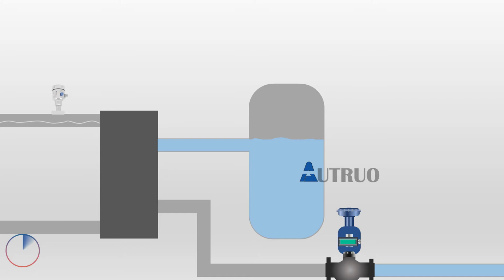The transmitter senses the pressure coming within. Once the required values have been reached, this triggers another process to happen within the loop. In this case, we are looking at valves. The valve opens and closes according to the pressure transmitter inputs. From the analogy discussed, we can see that the pressure transmitter is a critical part of a closed control loop system, because the instrument converts measurements to electric signals.